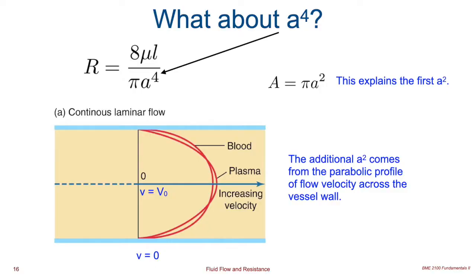Instead, we don't have a line of flow all at the same velocity. Instead, we have a distribution of velocities across that pipe. So when we have this distribution of flow rates across the pipe, as you see there, we can actually measure that too. We can put little flow meters or watch colored particles go by. There's different ways to measure this. And we will determine that the profile of that velocity, of that rate of flow of the liquid in the pipe like this, will have a parabolic shape. So instead of a flat wave moving at constant velocity, we will have a bent shape in which the middle portions are moving much more quickly than the portions of liquid at the edges.